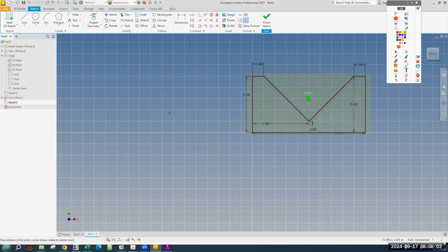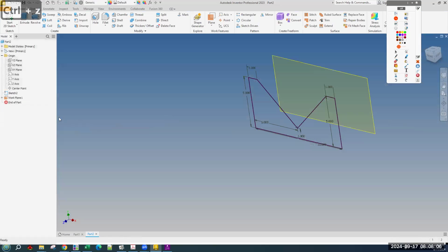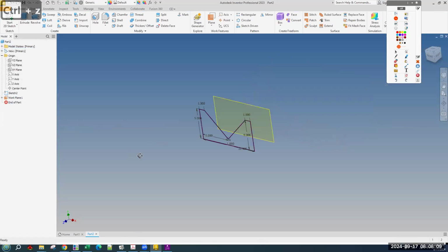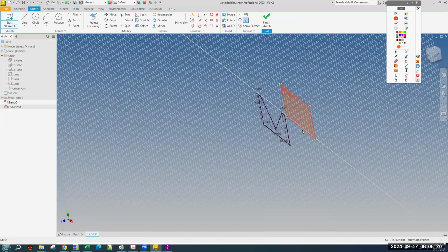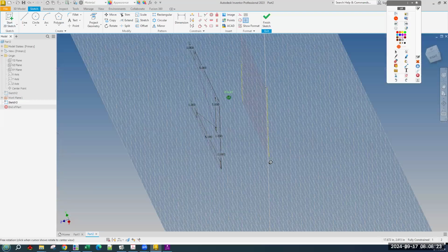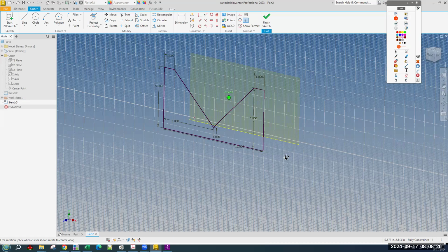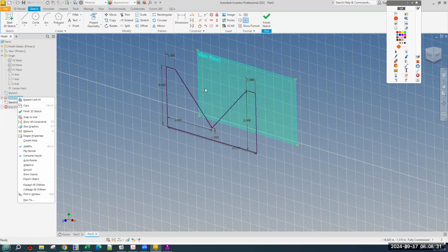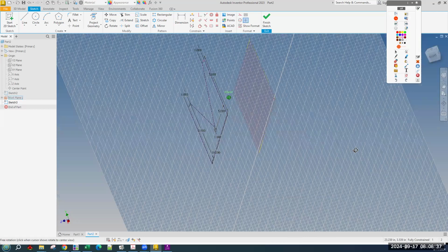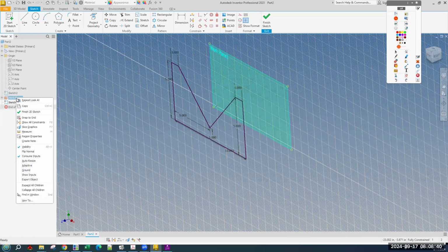Okay, so I've made my new, take a step back. Okay, I only have that going, and I'm gonna start a sketch. This is what I did a second ago. I lost where it was. Sketching here, and we are now sketching 4 inches behind our front, aka the back. And first thing we're going to do is turn off the visibility of work plane 1. Work plane 1 is just this yellow or would-be yellow rectangle that indicates that there's something there in space, and we don't need that square. So we're going to right-click and uncheck visibility.